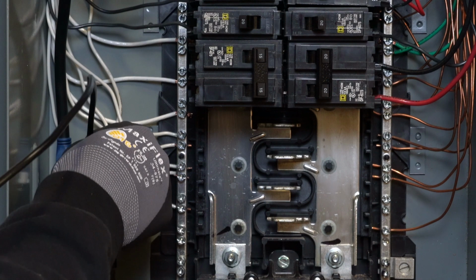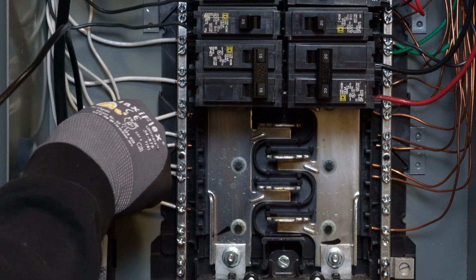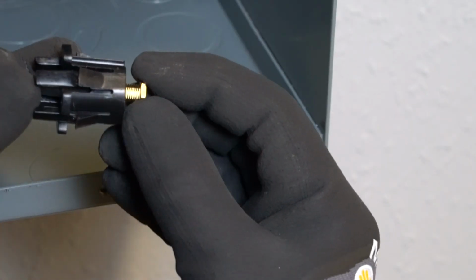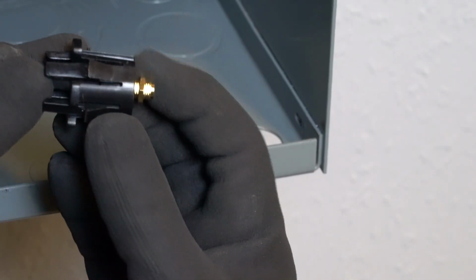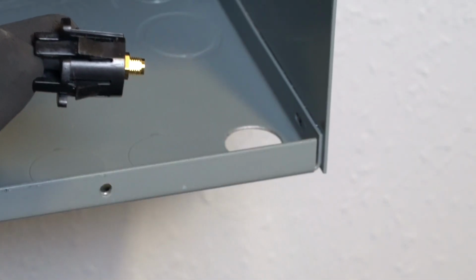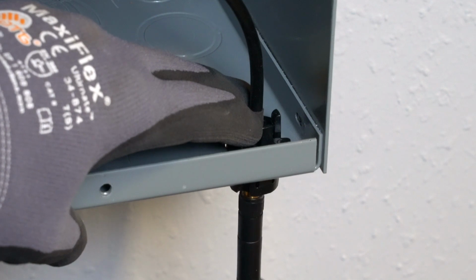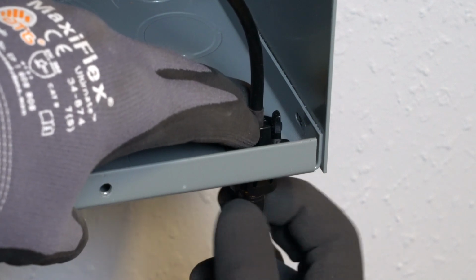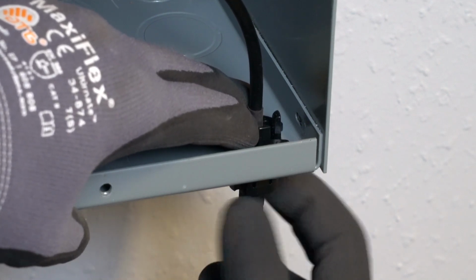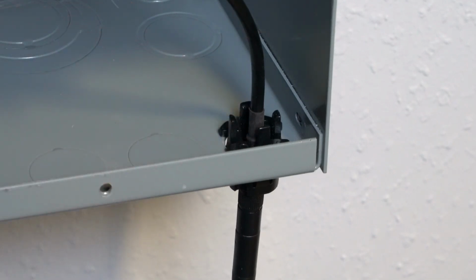When installing a remote meter, use the provided antenna extension to relocate the antenna to outside of the enclosure. Fasten the antenna extension cable to one of the provided antenna mounts, and feed this assembly through an open knockout that best fits the mount. Attach the antenna to the cable once the antenna mount is securely attached to the enclosure. This must be done in all instances where a remote meter is mounted inside of a metallic enclosure.